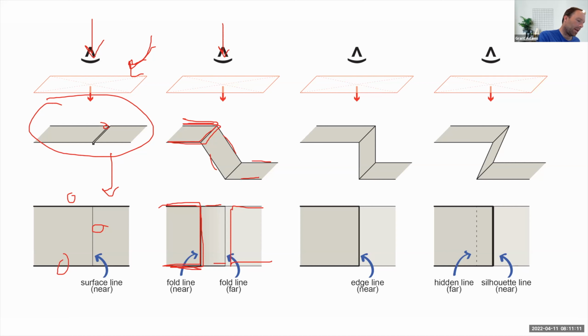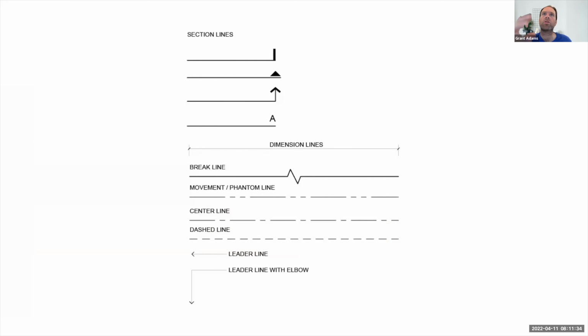If we go straight down with the jump like this, we have the bold lines right there and the thinner lines there and there. And this last one is where this kind of tucks back underneath, in which case we're seeing a hidden line, the dashed line. That's the representation of the dashed line here, represents that something is folded under. So it's a good illustration of what's happening.